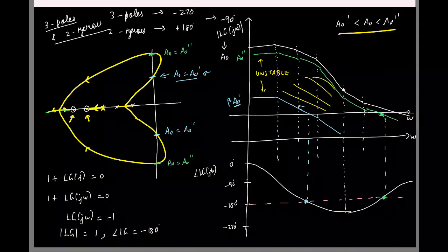Yeah, that is okay. That doesn't say anything about instability, right? Minus 180 phase doesn't say anything about roots in the right half of the S plane. If the phase is 180 and the gain is 1, it just says we have roots on the imaginary axis. That's all. Having roots on the imaginary axis doesn't imply that it will go to the right hand side. As of now, the only information about instability is that if the poles are on the right half of the S plane, it is unstable. That's all.